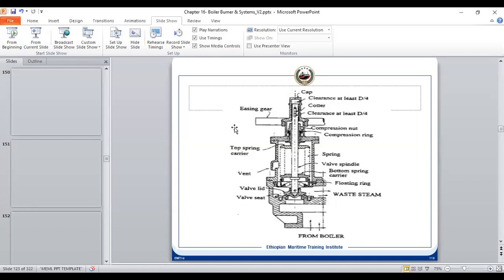Now, once you are coming to this time of 3 years, that has to coincide with either the vessel's dry docking, which is normally every 5 years. The actual dry docking, I'm not talking about the in-water survey. The periodicity of the in-water survey is normally 30 months. But at 30,